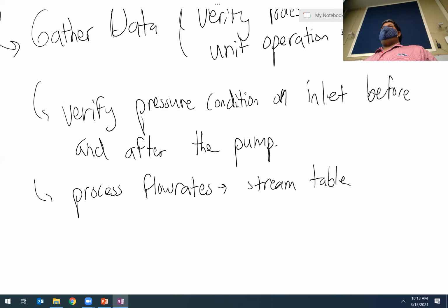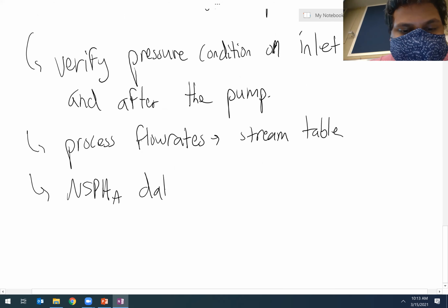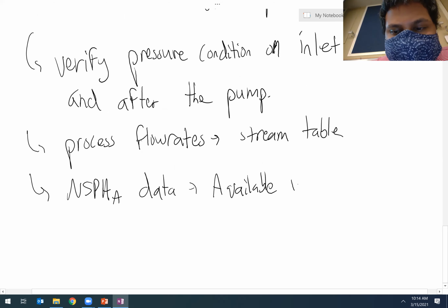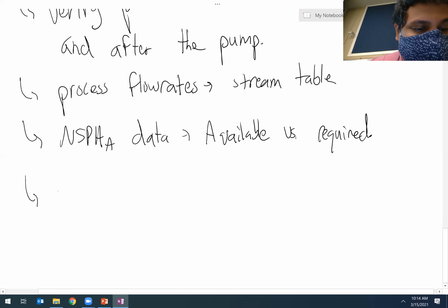I don't know how close we were operating before the calculation was. Okay, so you'd be interested in NPSH A, or available, versus required. Okay, what else? Go ahead. With the temperature that went down at the pump. Temperatures in and out of the pump.